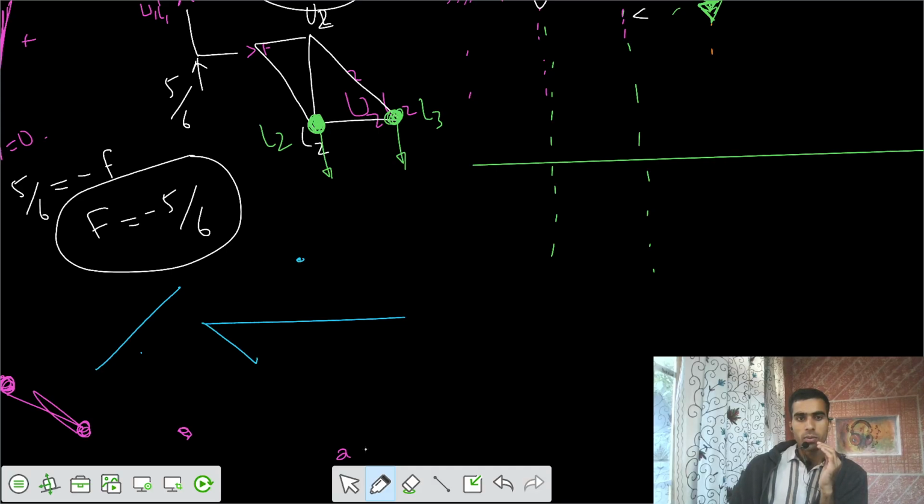We have one of the ordinates above the line and one of the ordinates below the line, such that the final value here is some value of xd by L into h, and similarly here is also some value of xd by L h. X is in this direction, here x is in this direction. And this was the case of a diagonal member.